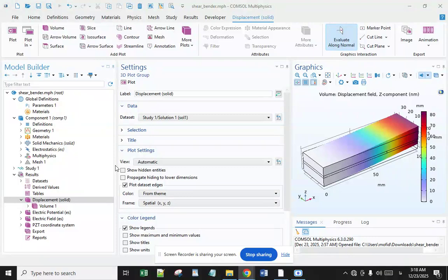Vibration analysis of both actuation mechanisms was presented through evaluation of natural bending frequencies and modes. Vibration modes are equivalent in both mechanisms; nevertheless, shear actuators are less deformed than extension ones, and natural frequencies are higher for extension actuation mechanisms. The present work is being extended to implement the sensing capacity of the adaptive sandwich beam in order to study active control applications.